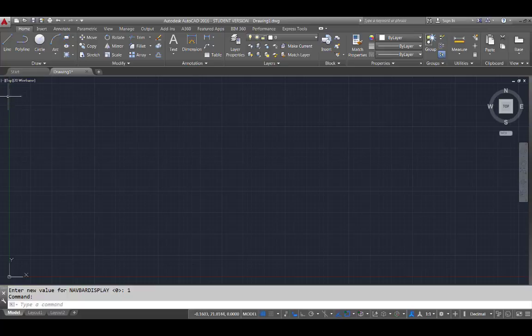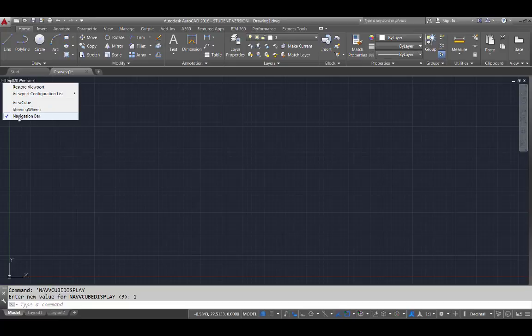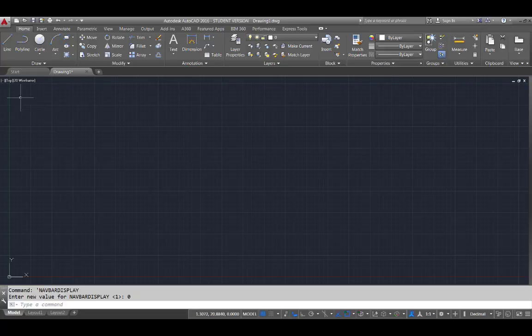And if we go over to the far upper left, we see some other little commands and little brackets here. One is a little flat bar, and if we open that, notice that in that little pull down we see view cube and navigation bar clicked on. If we click those off, they'll disappear, and we'll just get a little more open real estate to draw in, and that can be helpful, especially when we're getting into kind of complex drawings.